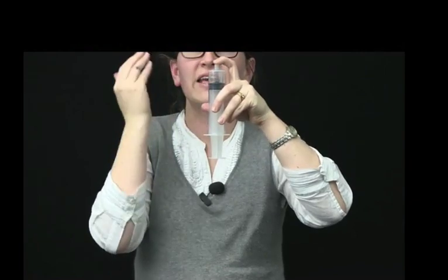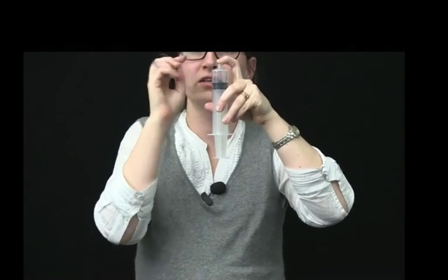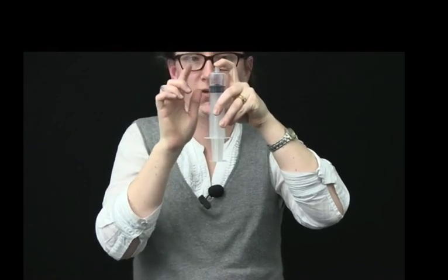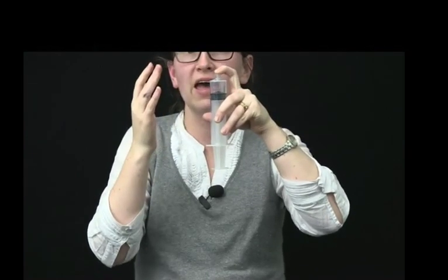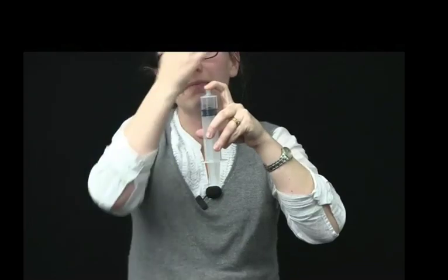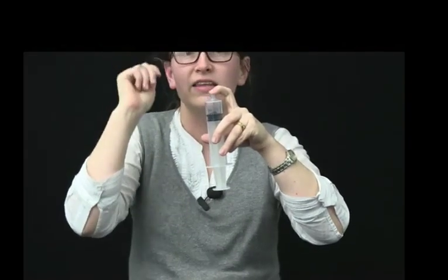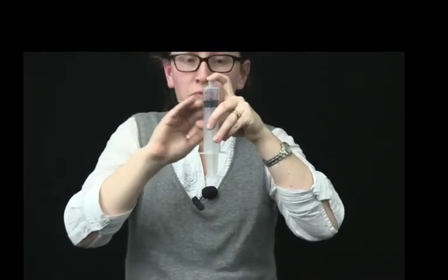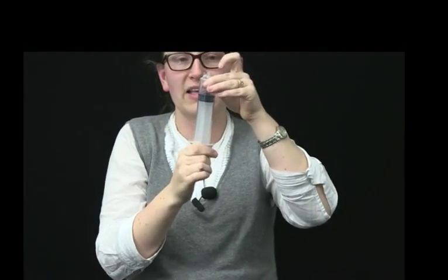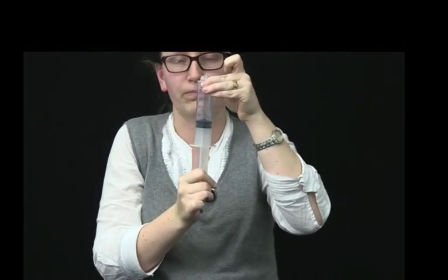The car then ignites the spark plugs. So these cause a spark to take place in that mixture of fuel and air. And when that happens, the temperature increases very rapidly. And we've seen from the ideal gas law, PV equals nRT, that if the temperature goes up, then the volume goes up. So at that point, the gas here does work on the piston and the gas all expands and the piston moves downwards.